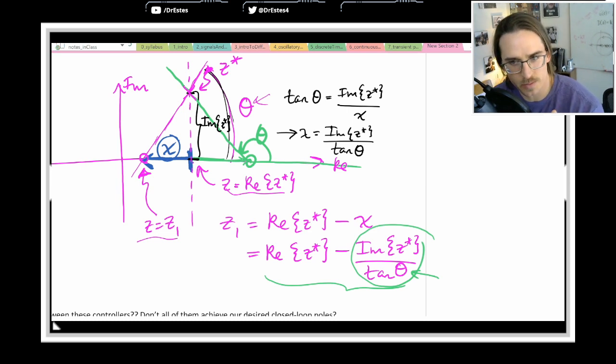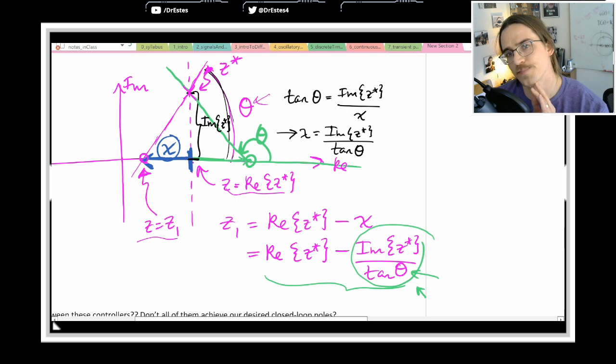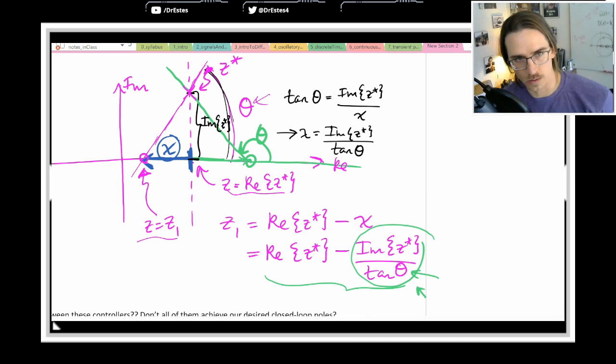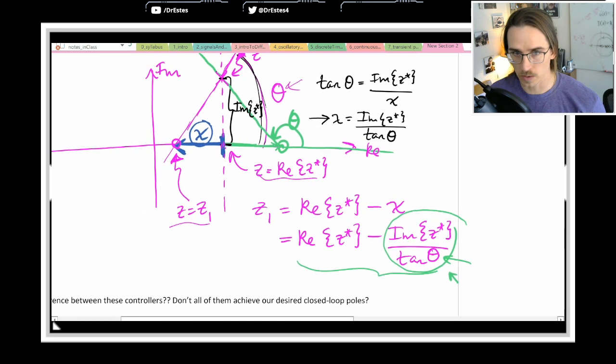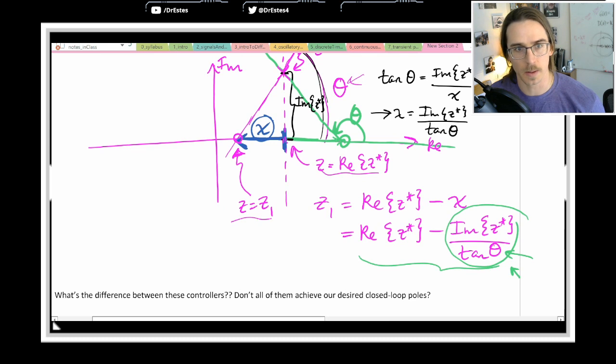That doesn't make sense when I'm saying that right now. But let's say you're looking for the location of a pole, and I know a pole is going to contribute, let's make up, minus 45 degrees. You could use this same formula, but instead of inputting negative 45 here, you would put positive 45. So maybe we'll come back to that, but tuck that away. This still works for a pole. You just have to make a small adjustment.